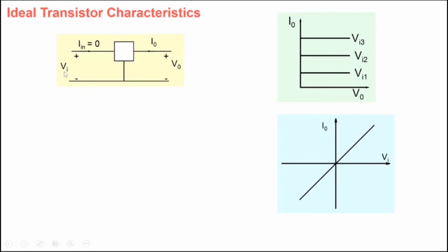So remember, in our discussion of triodes and transistors, we said output current is sensitive to voltage applied across another pair of terminals, that is transconductance, while output current is not that sensitive to output voltage, which is the output conductance. So these are like the transistor characteristics. This device has finite transconductance, but output conductance is 0, so obviously transconductance is very, very high compared to output conductance. So this is the element, and we are saying that this is like an ideal transistor characteristic.